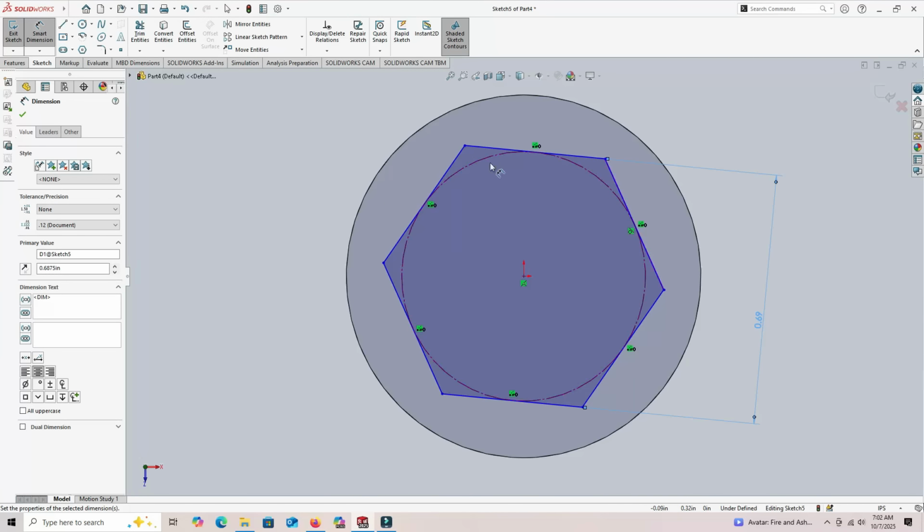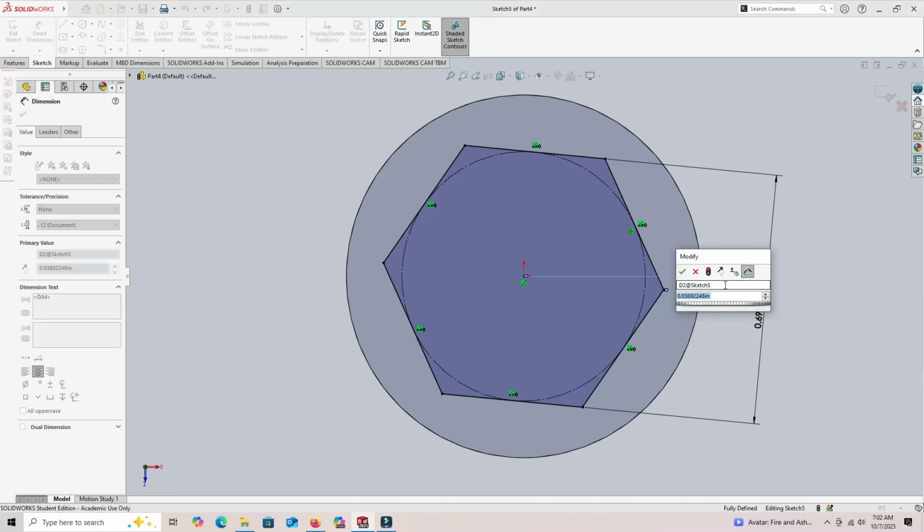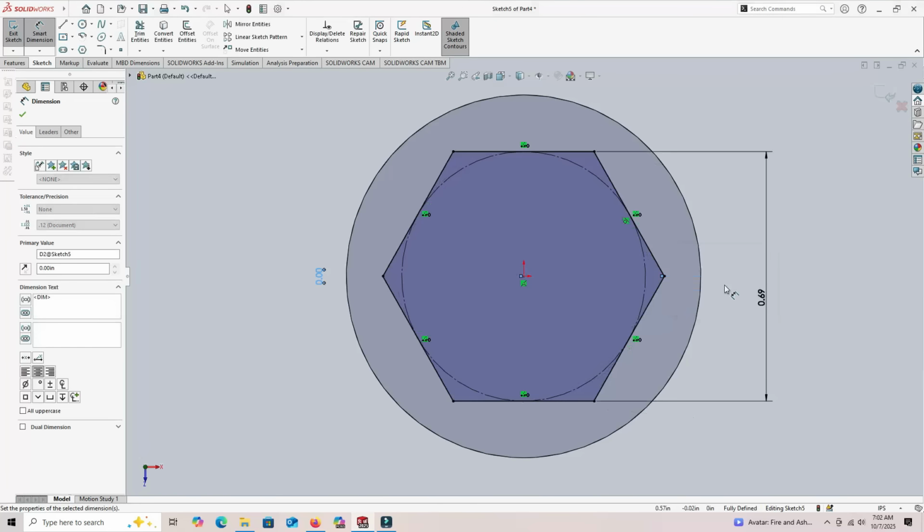I want to then do this. I want to make sure that is listed as 0, so it snaps it around to this 0-degree mark. I could have done that as a horizontal relationship between those 2 points using the Add Relationships button, but instead I just sort of clicked out in the field at a spot that was not snapped to 0, and then I could just use Smart Dimension.